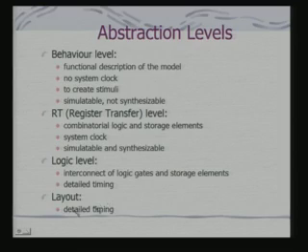So, when you want to add functionality to that processor, depending on your system design, you add a module to the VHDL specification of the processor. So, you have an enhanced hardware. If it is an absolute hardware core, that means you may have the layout level design available with you. So, you add functionality to the system and maybe design an ASIC or an ASIP as the case may be.